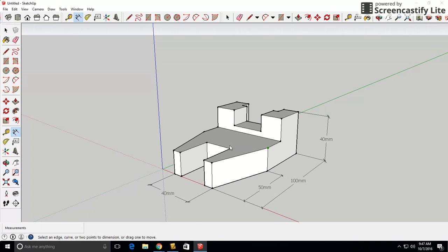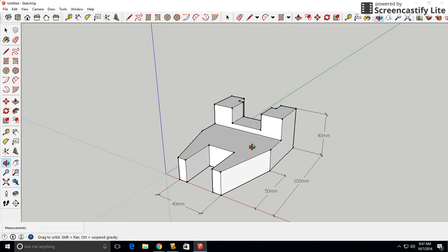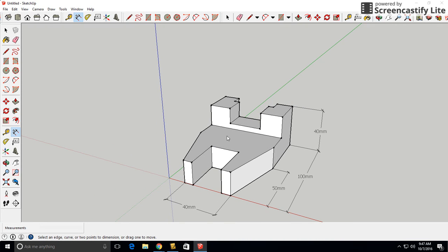Now, in this drawing, they also dimensioned on top. I would tell you that when possible, you should avoid using dimensions on the object. It gets confusing, it's difficult to see, but in some cases, it's unavoidable. So the overall width of this object, we dimensioned from the corner of the jaw to the corner of the jaw there at a distance of 70. You could drag this up, but that's going to add more confusion to the drawing. So I'm going to leave that dimension live on top of our drawing.